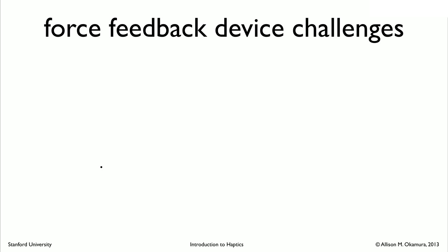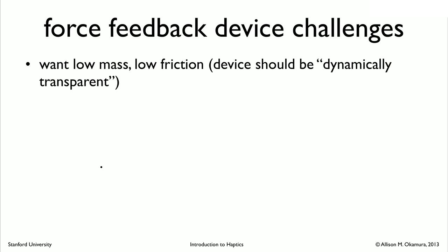Let's review some of the main challenges in designing force feedback devices. Some of these will become clear as you do your kinematic analysis and you actually construct your hap kit. The first is that you want the haptic device to have low mass and low friction. This is because the device should be dynamically transparent.